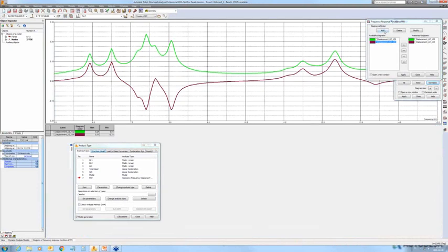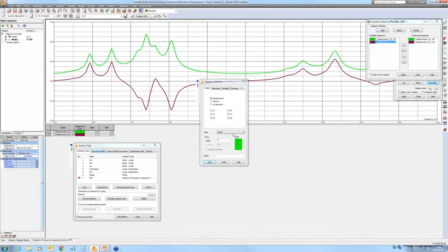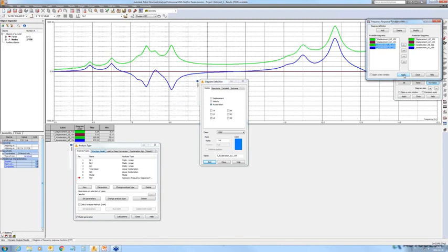We can also add the information about acceleration. So, okay, vertical acceleration in node 132 and 154. And I will move them to the diagram. As you can see, the magnitude is much larger than the displacements. So I will remove the displacements from the diagram.